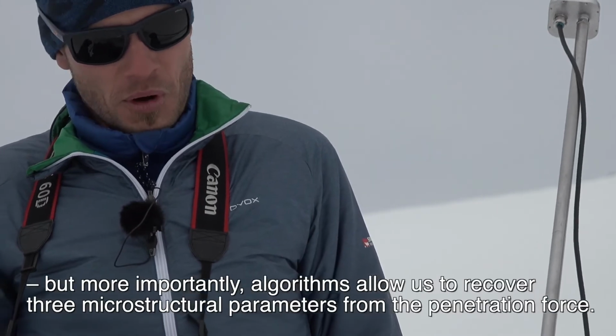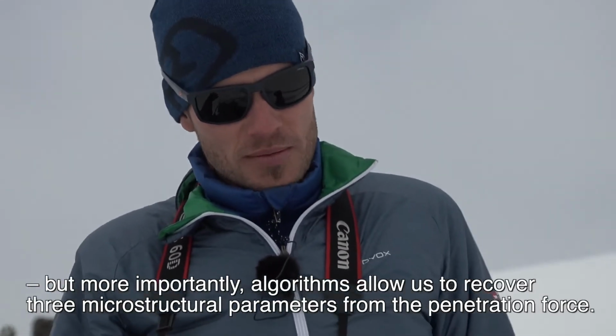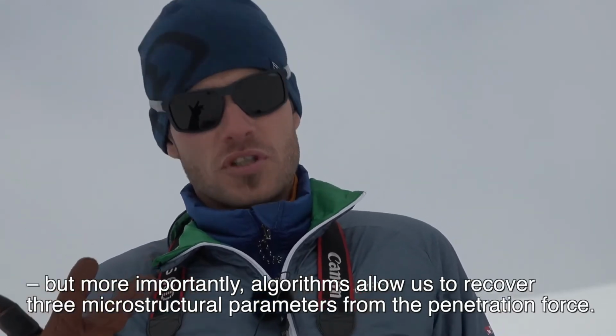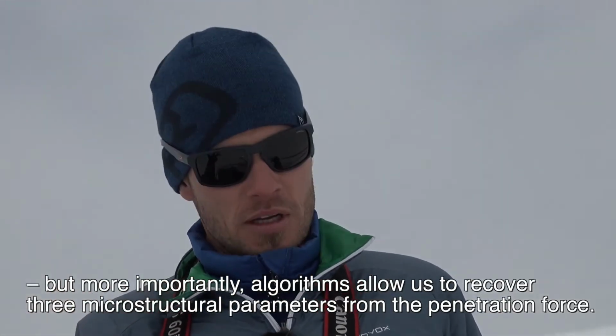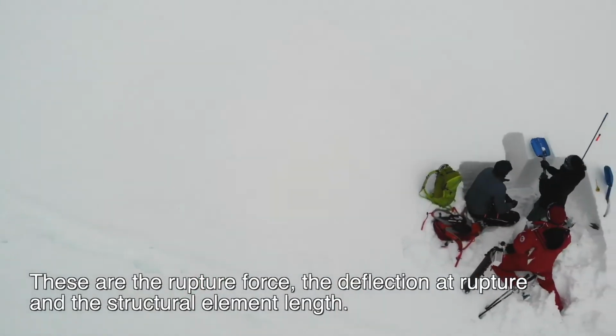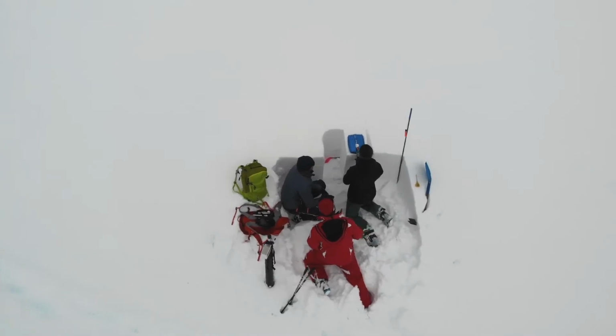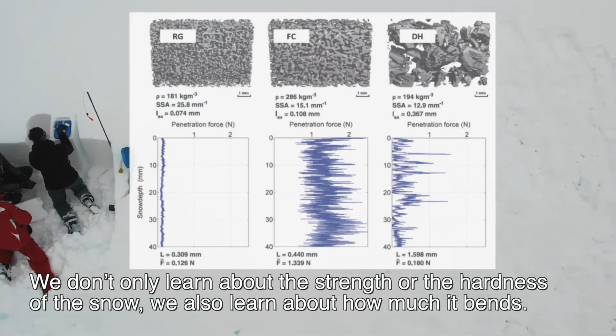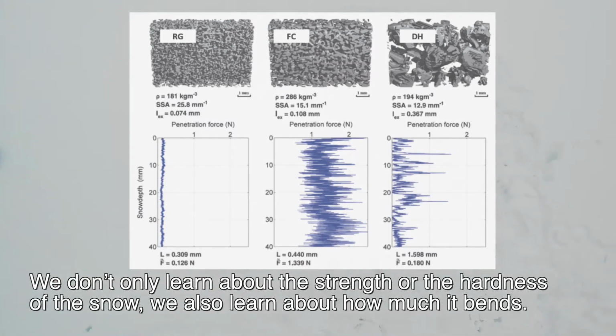But more importantly, algorithms allow us to recover 3 microstructural parameters from the penetration force, which are the rupture force, the deflection at rupture, and a structural element length. And now you actually see what is really the nice thing about it: we don't only learn about the strength or the hardness of the snow, we also learn about how much it bends.